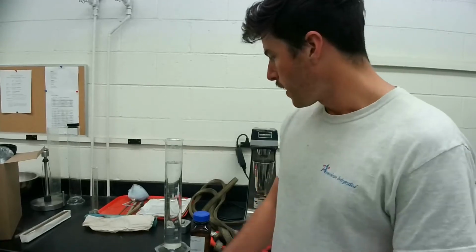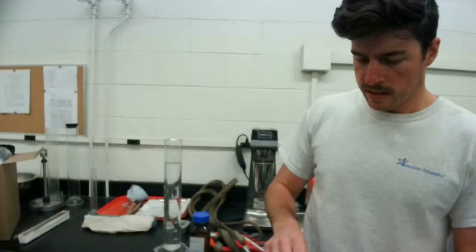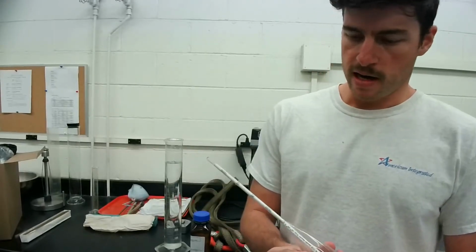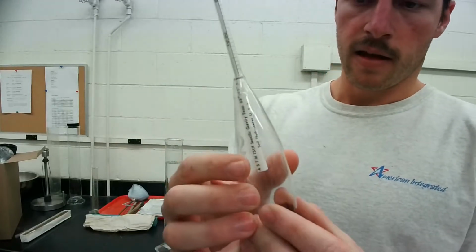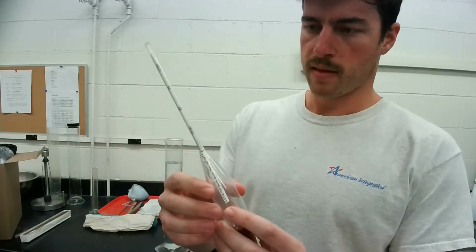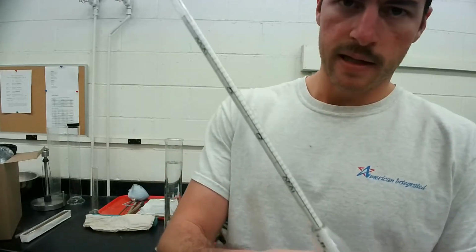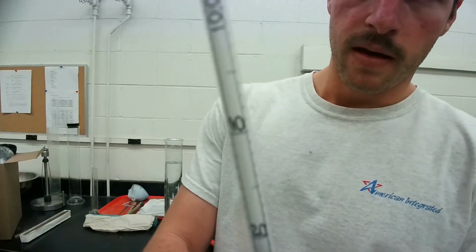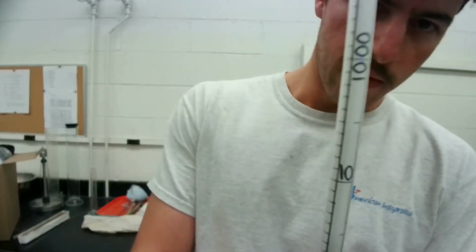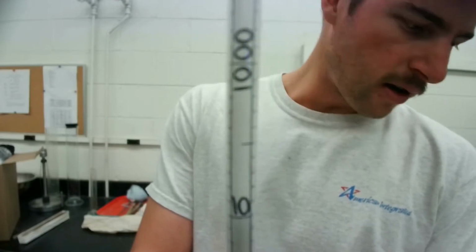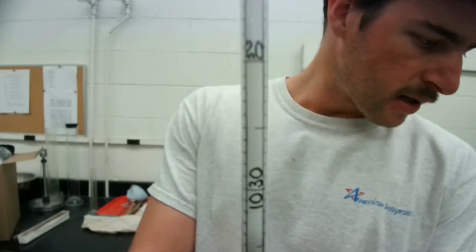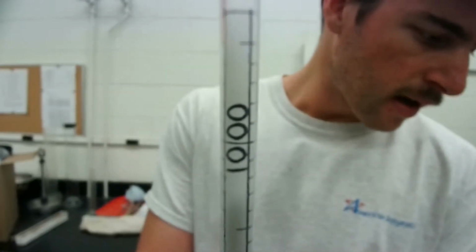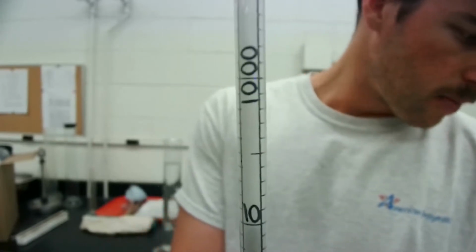To do that, we need a hydrometer, which is this device right here. It's a glass tube. It has a bigger volume here at the bottom that'll cause it to float. And here are the markings along it, right? All these markings on it are what in the lab manual are called R sub T. These are the actual markings on that. And so that's what you'll be reading when you are measuring the hydrometer in the soil water mixture.